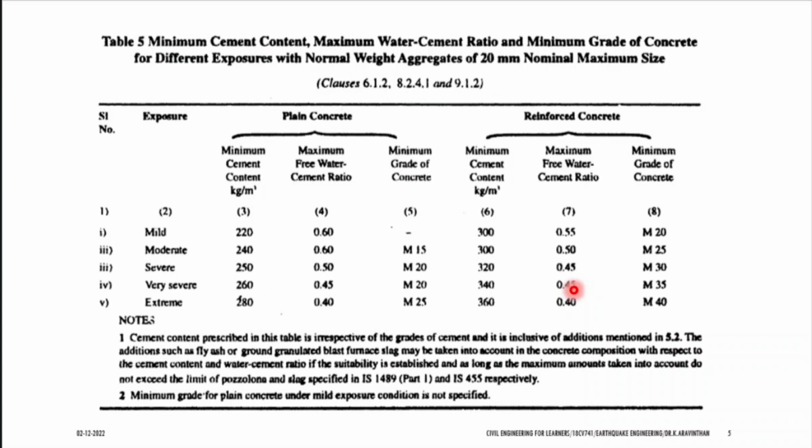Today you will not know, but the client will call you after some years. If you are installing just a 1000 liter water tank, they will call you. After some days, there will be cracks in the roof. They don't know for what reason the crack comes. When you go for inspection, you will know. They think it is a different reason, but the reason is this one.